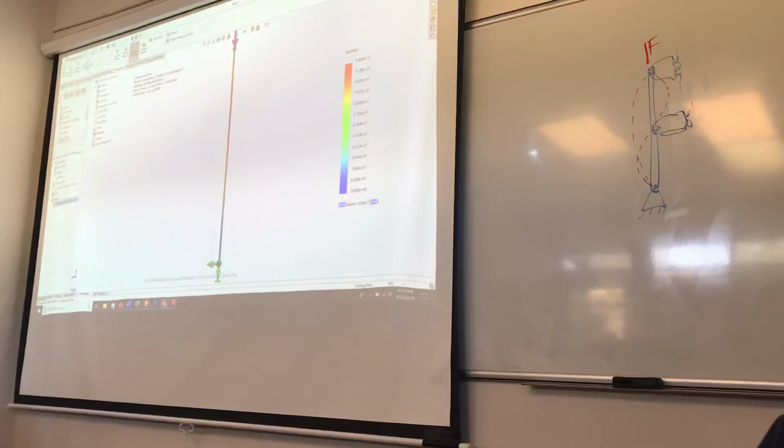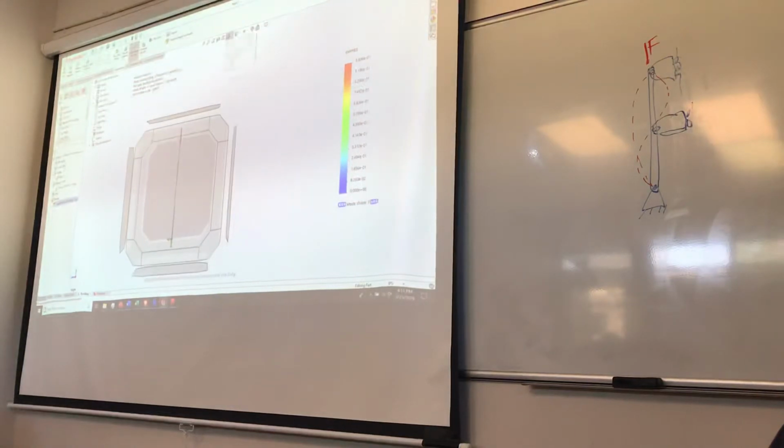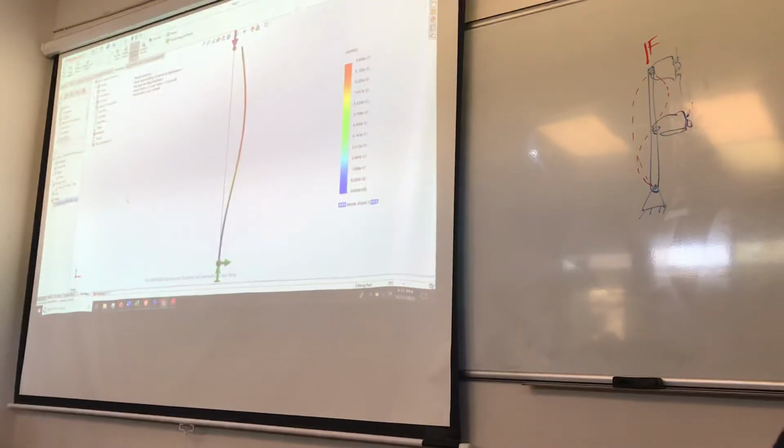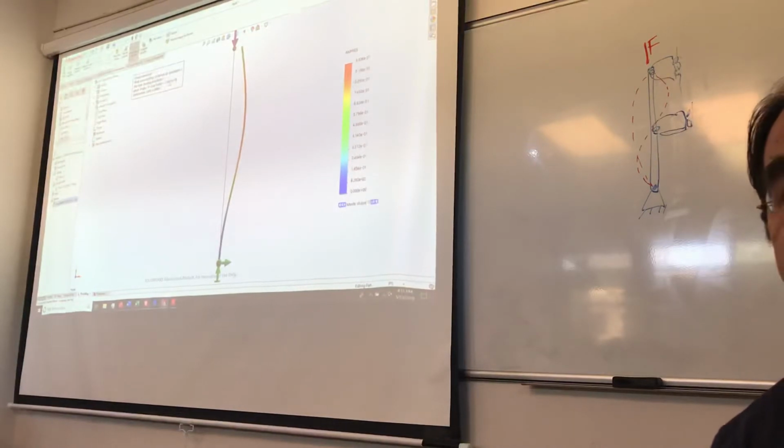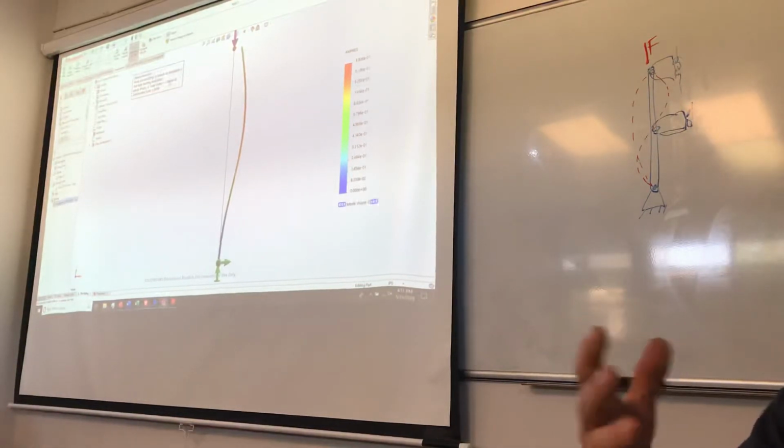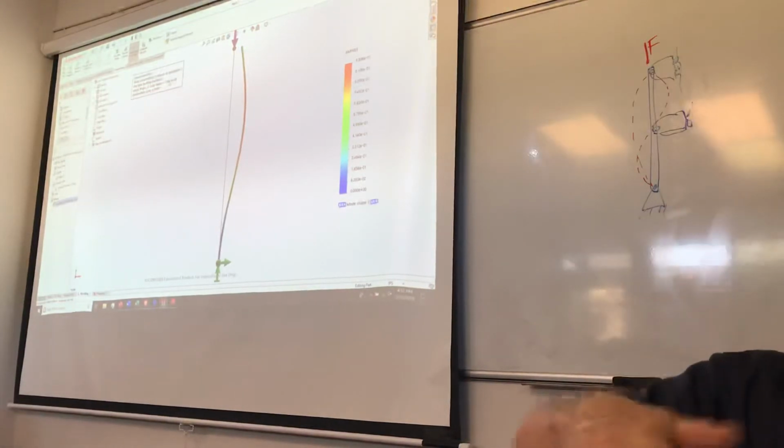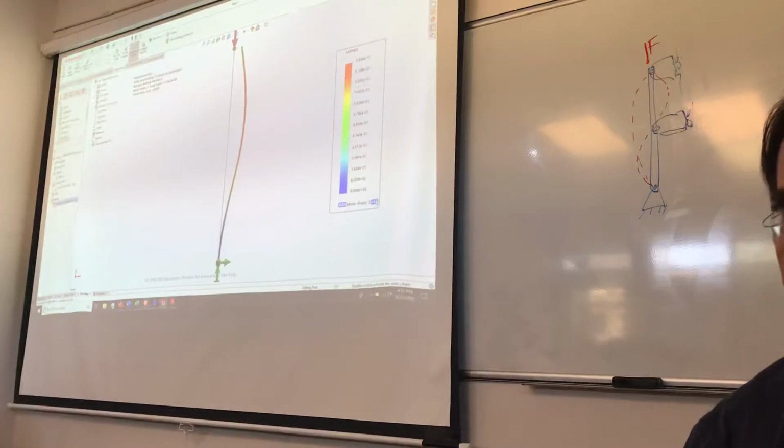Here we have the third mode, and let's go to the fourth mode, just because it's going to be in one of these other planes, right? Oh, it's not deforming very much. That's because the scale's not very big. But come on, is it in one of those? There it is. There's the next mode up, right? See, it's deforming at 100,000 pounds instead of at 30,000 pounds, and that's the mode that'll be in the skinny direction, but it's the more complex mode, and we'll just follow them on up now.